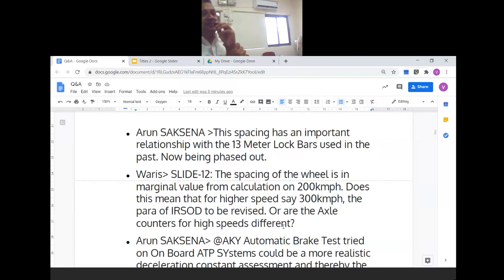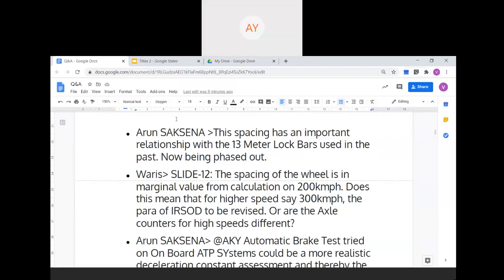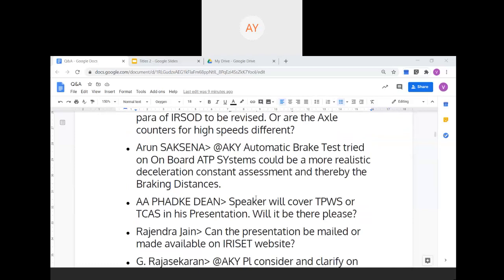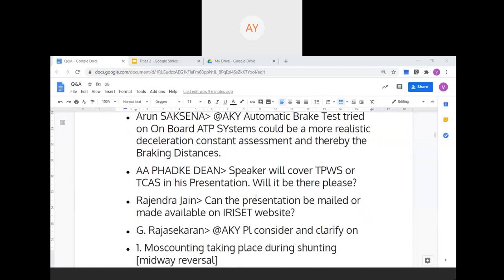You have to identify that the 25.9 millisecond limit of interaxle distance is the worst case for one worst kind of sensor among all those available in Europe. We have to see in our case what is our worst case, and then define the limit. I have calculated, for example, at 200 kmph. We are running trains at much less than that at this moment. Even up to 250 kmph, I think that distance is all right. That interaxle distance is also for some specific rolling stock. Otherwise, for passenger rolling stock, it is much higher.